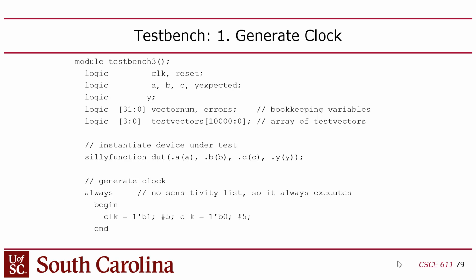Now in C, if you declare a two-dimensional array, what goes first? The rows, then the columns, right? So if I declare an array in C, and the first number I put in the array is 10, and the second number is 20, that's 10 rows, 20 columns. Same thing in linear algebra, math uses that too. It's always rows and then columns whenever you have a two-dimensional array. In Verilog, they switch them. They're backwards.